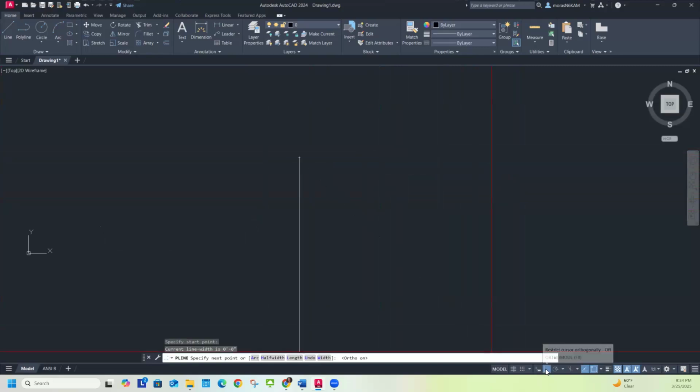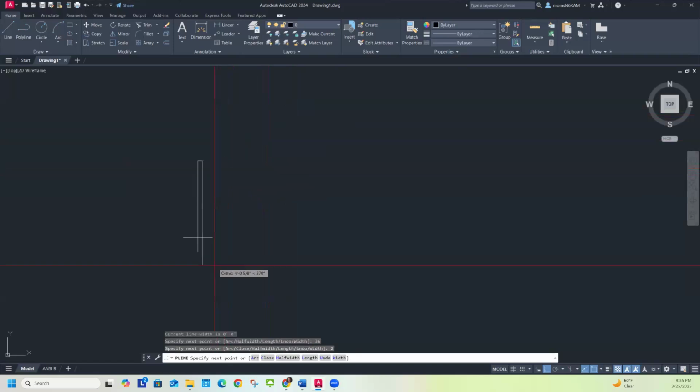And so, oops, I'm going to go ahead and start drawing that. Let me turn on ortho mode, and actually while I'm here I'm going to turn on a couple object snaps. And actually I have everything I want to have on, so I'm just going to leave it as that. Here, let me try that again. So I'm going to go to polyline, and this is going to be 36 inches. And then by 2 inches.